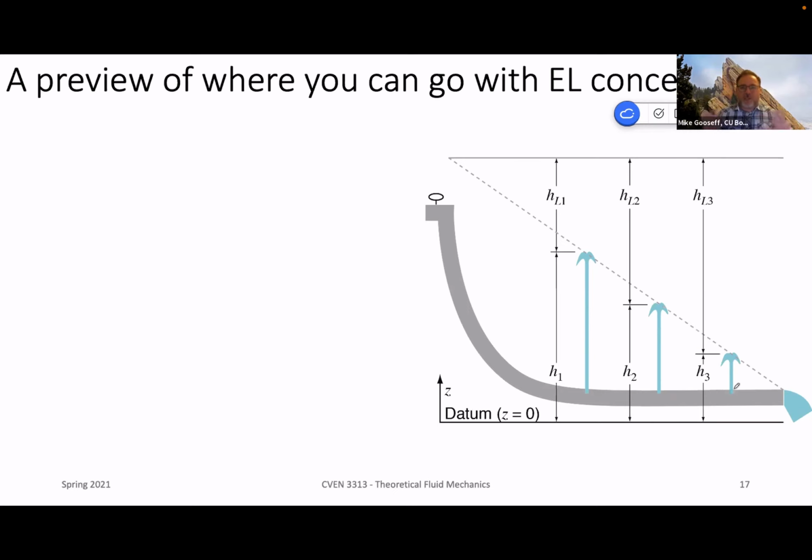But even if we just ignore that loss for a moment, the energy is going to change as we move downstream when we start to include the losses due to things like friction, the friction between the fluid moving in the hose and the hose walls. And that's often going to be provided. Now our energy line is going to look something like this, perhaps, that we drop off because of these losses that occur. If we were to put in, let's say, a turbine or a pump or something like that, we'd have some other discontinuity in our energy line. And so I just